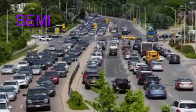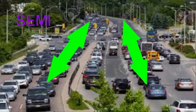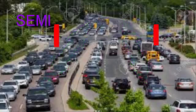Semi-actuated controllers are used for major roads that have a constant flow of traffic throughout the day. Their main function is to prioritize traffic on bigger roads by controlling the light intervals of smaller roads. They receive information from detectors installed on the smaller roads so that they are able to give the right-of-way to vehicles on the smaller streets when necessary, while keeping minimal disruption to the flow on the larger street.